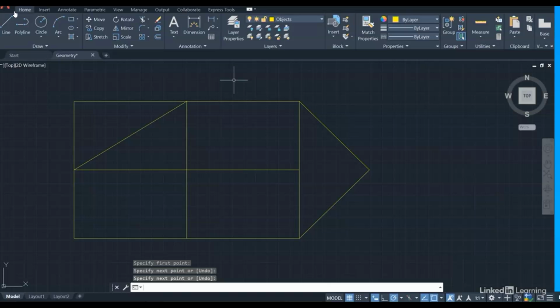Now you can draw a line slightly differently. Let's press spacebar or enter to repeat the line command. It's asking for the first point again. I'm going to start where I started before, here. There's the endpoint, left click, and my line kicks in like so.